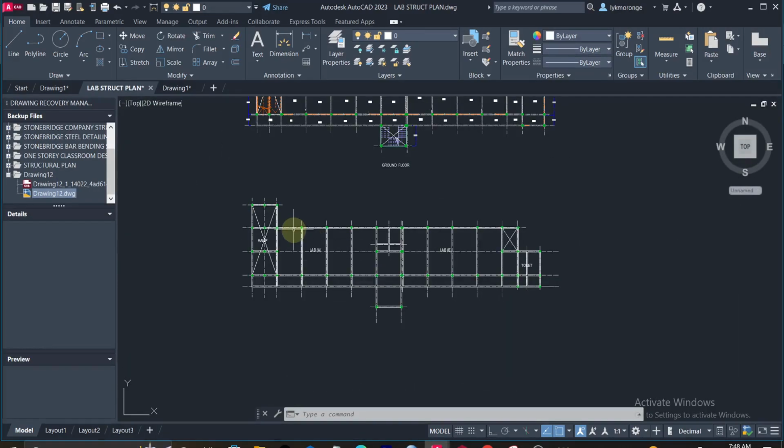What you do now, you save it as a DXF file. So this is where our lesson is ending, by saving our model. Our subsequent lesson will now be on how to import this model to ProtaStructure. So I can just highlight everything on the model now that you have prepared your structural model.